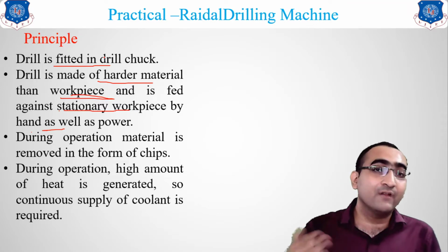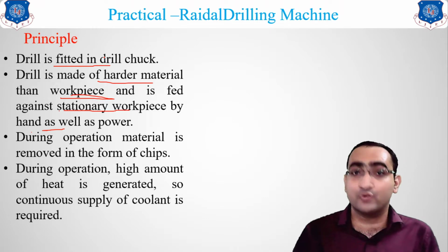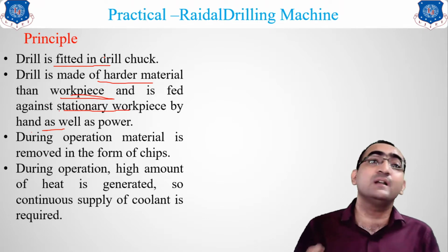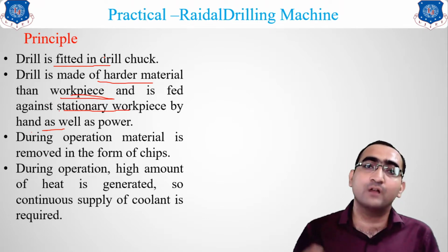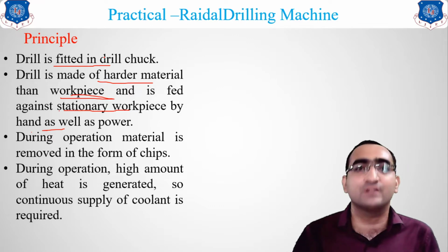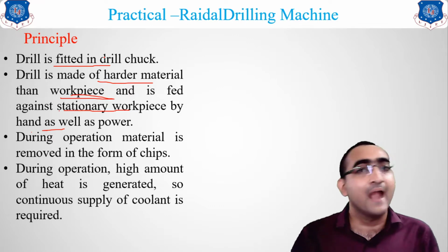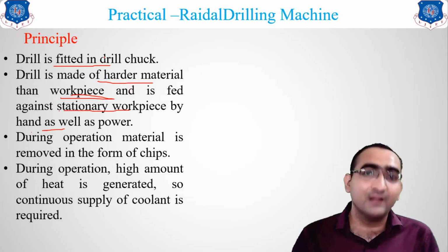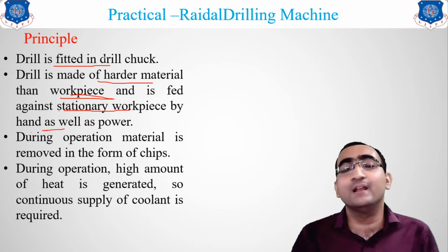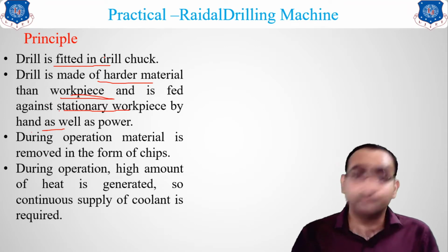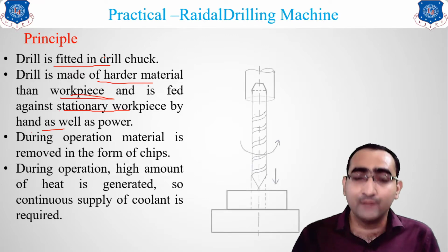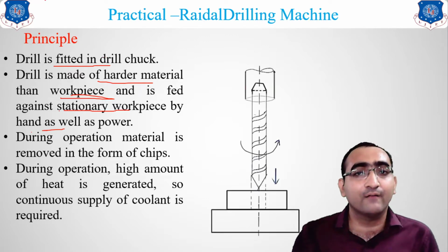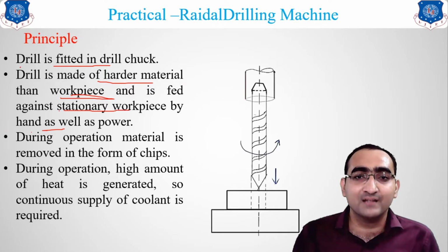So whenever you are drilling any metal, coolant is required, because maximum heat is generated during the metal and tool interaction. If you are drilling wooden material, it's okay, you don't require the coolant, but for metal you require it.